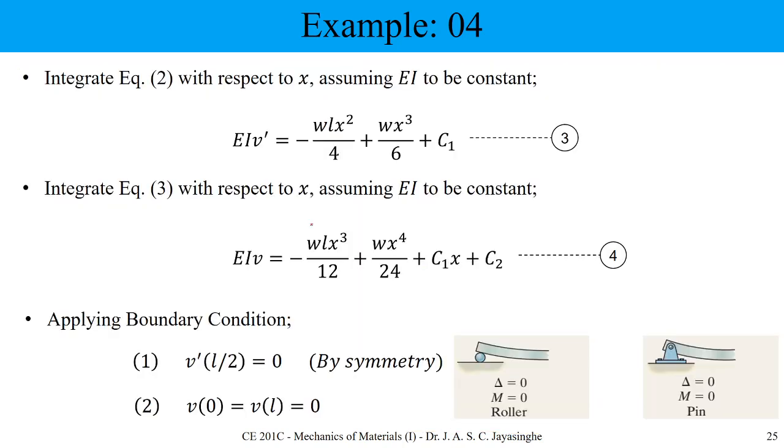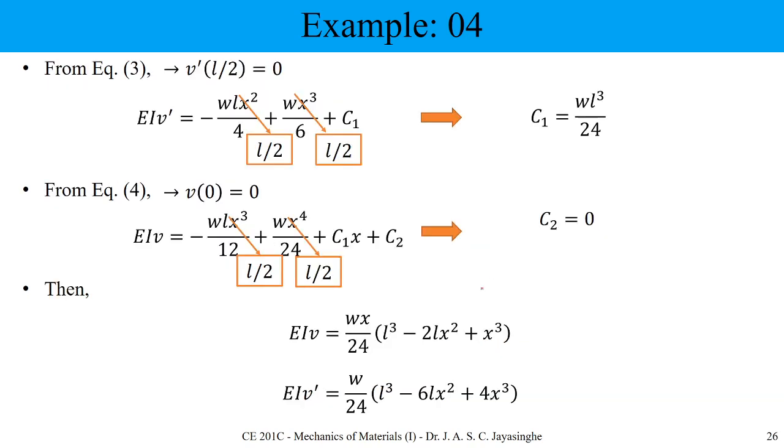Okay, and here I'm going with the bending moment case. You can substitute here, one integration will give this value, another integration will give this value. You mainly have 3 primary boundary conditions, and you can select any 2, substitute, and find c1 and c2. Here we can find c1 and here we can find c2, and you will end up with the variation of v, deflection, and the variation of theta.